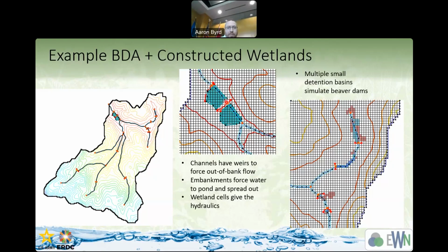I also spent some time when I went through last night. I made sure that my stream was pretty shallow next to the land surface, so that when the water came down, it could actually overflow into it. And right here and right here, where the stream would exit the berm, I put a weir in there so that it would back up the water into the channel and then from the channel up to the overflow. So you have to think through the sequence of all the parts and pieces it takes to move the water to where you want it.